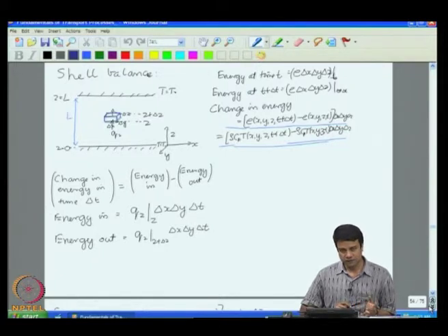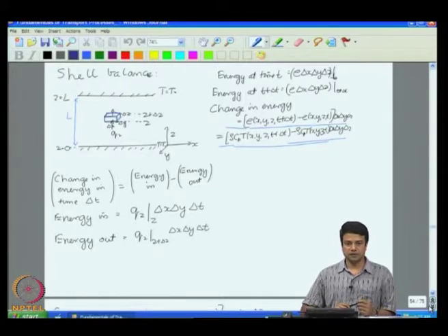One could have phase change, in which case there is a latent heat of phase transformation which has to be included, and there could even be mechanical sources of energy. For example, in a pipe, if you have a viscous fluid flowing, then there is fluid friction, shear stresses, and that itself generates heat, and all the energy that goes into pumping that fluid gets converted into heat energy and thereby increases the temperature of the system.